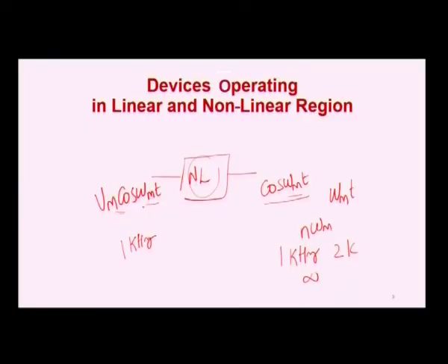This principle can be used for a frequency multiplier, or to raise the level of the frequency. Using this concept, we are going to see the balanced modulator. Here we have seen only one frequency component applied to a non-linear circuit. If we apply two frequencies, what happens? Let us consider that we apply another signal, cos omega ct, another frequency, to a non-linear circuit.